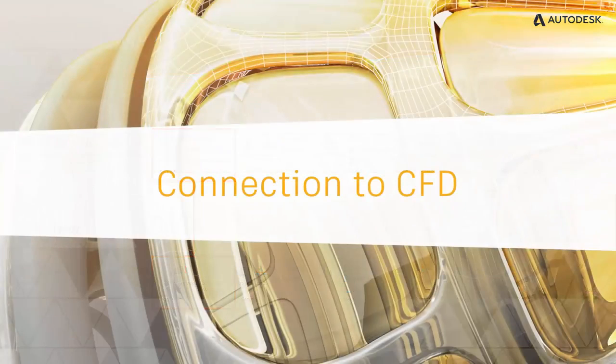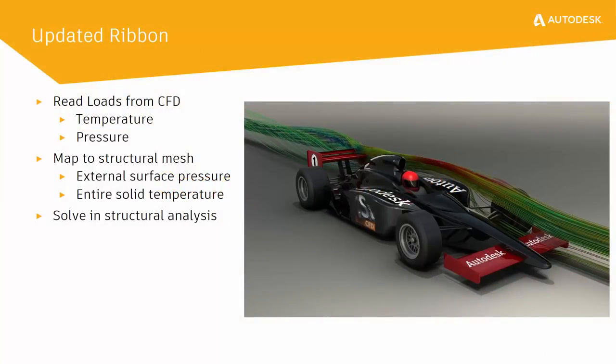Another exciting improvement is that you can now connect your results from Autodesk CFD to your Nastran in CAD designs. This means that thermal or pressure loads from your temperature and fluid flow profiles can now be easily included in your mechanical stress analyses as well. Both temperature and pressure values can be carried over to Autodesk Nastran in CAD. Since the meshes on your parts will be different, a mapping process is used to take the results from the CFD mesh and map them to the corresponding mesh in Autodesk Nastran in CAD. This can map external surface pressures and the entire temperature profile for the solid model, then being included in your structural analysis.